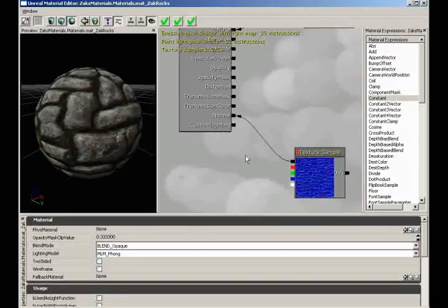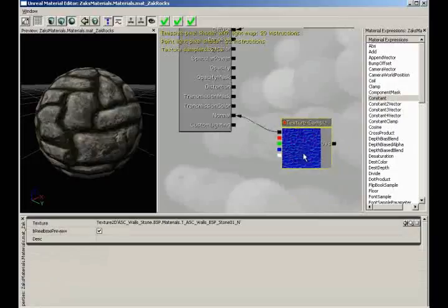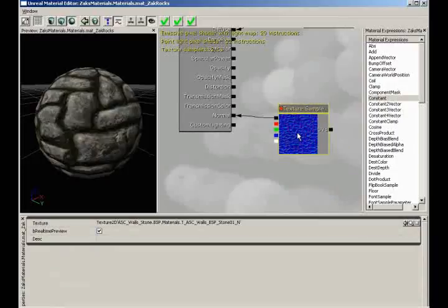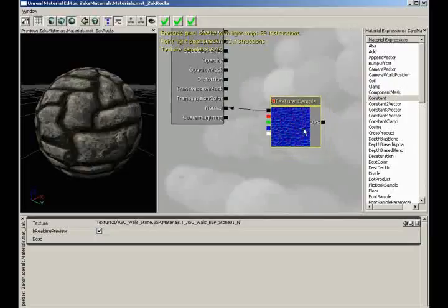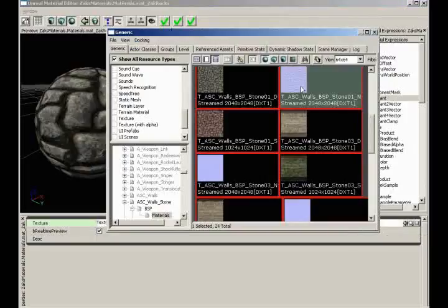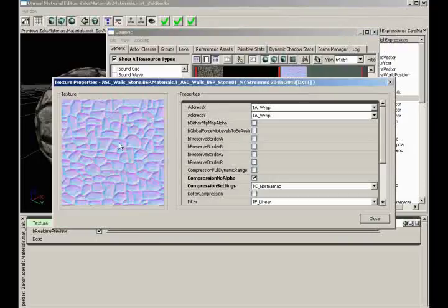Now down from here we have normal, which in essence we've already covered, but I'll give you a little bit more of a description of it. A normal map is a special texture that has surface depth information, and it works in all 3 axes. I can't really open this up and make it bigger, but what I can do is open up our generic browser, and I can double-click on this guy, and you can take a closer look at this normal map. You'll notice that you have some red here along some of the top areas. It actually gives it a nice 3-dimensional look.